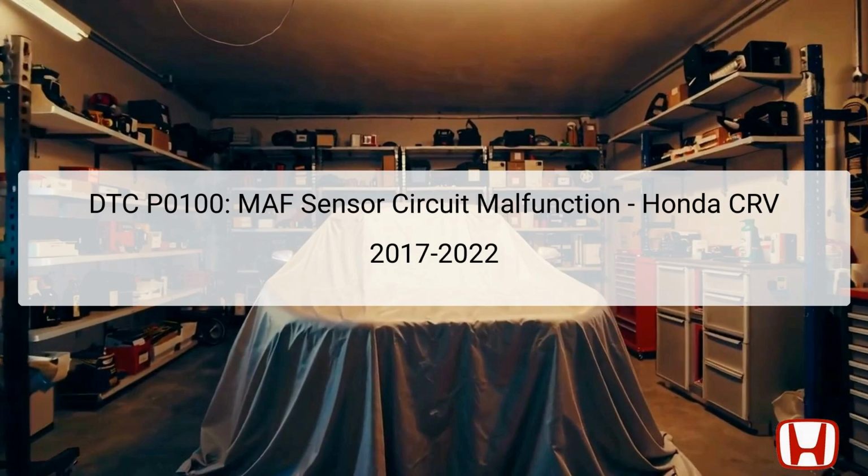DTC P0100 refers to a problem detected in the mass airflow (MAF) sensor circuit of the Honda CRV models from 2017 to 2022. The mass airflow sensor plays a crucial role in measuring the amount of air entering the engine, informing the engine control unit, ECU, of the correct air-fuel mixture. If the ECU receives inaccurate readings, it can lead to performance issues such as rough idling and reduced fuel efficiency.